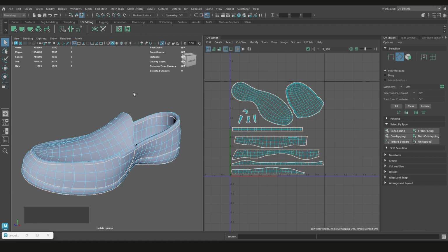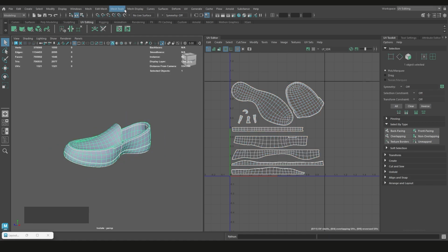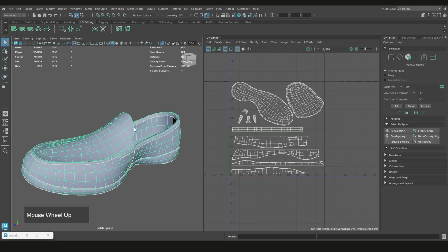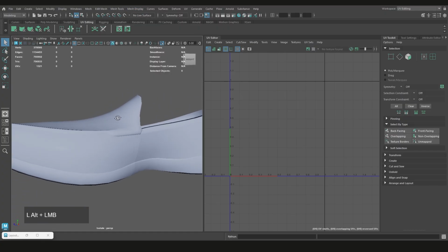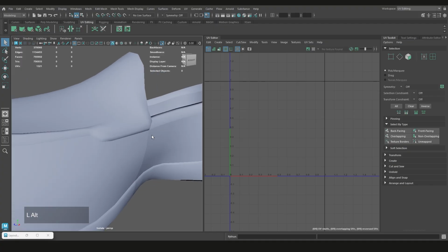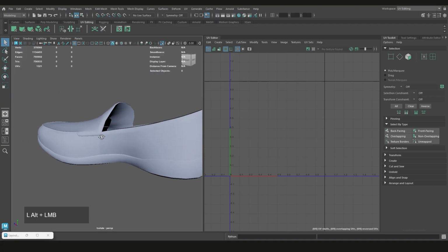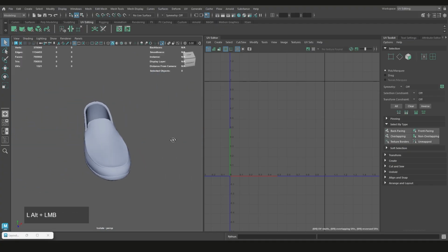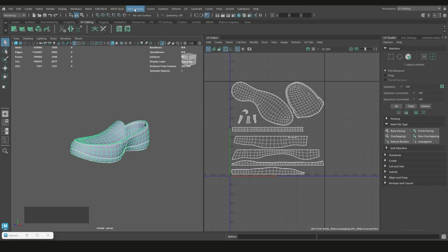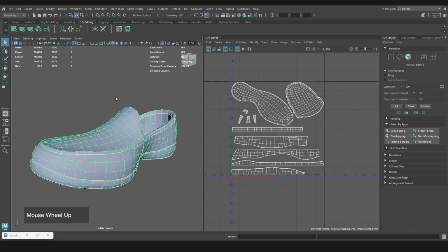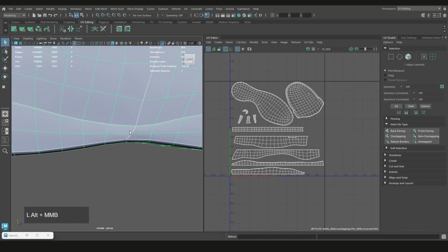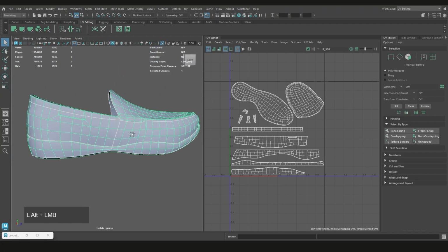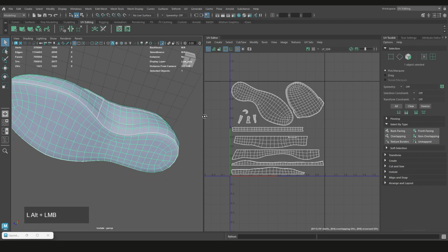Okay, and then object mode, mesh display, unlock those normals, and there we go, so that did work, right? Now you'll notice that we've got these seams here that are now hard edges, which looks a little bit distracting. What I do want to do actually is go back here and say mesh display and lock those normals. Okay, and now this will just aid us in our baking. Again, that looks a little bit distracting because we have hard edges where the seams are, but that just helps us out in terms of baking.